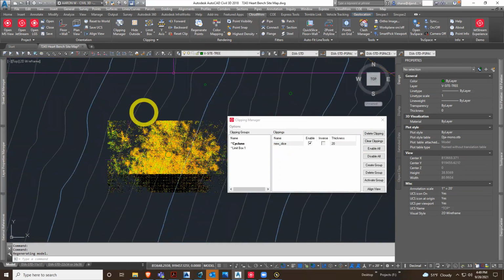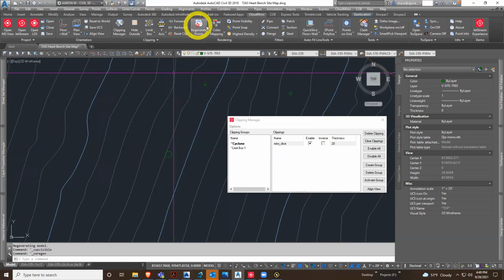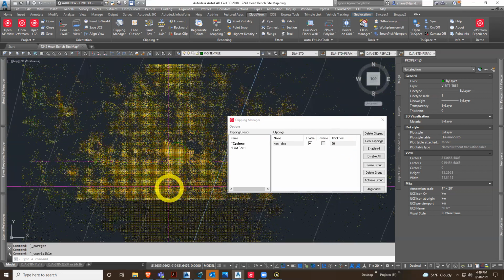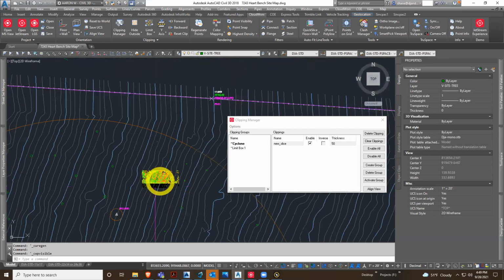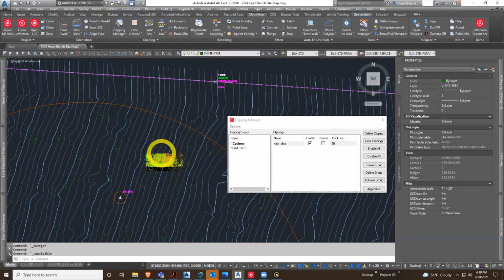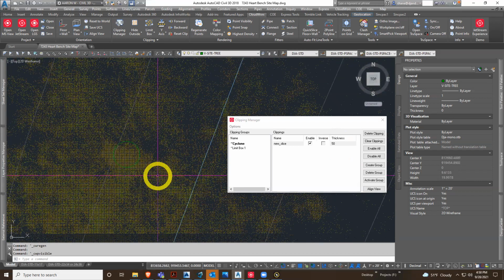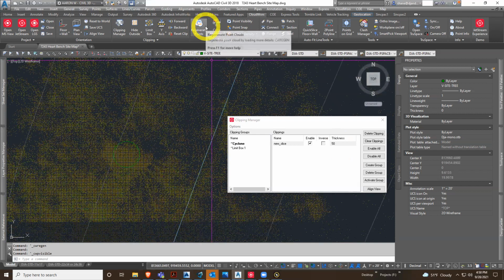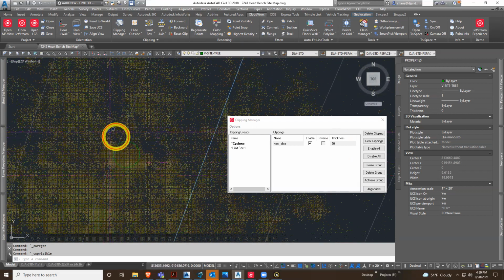Should be updating the view. I think I got it to update there by hitting visibility on and off. It's essentially how we place the trees. We're just slicing these, regenerating at strategic points to get these to look more like trunks.